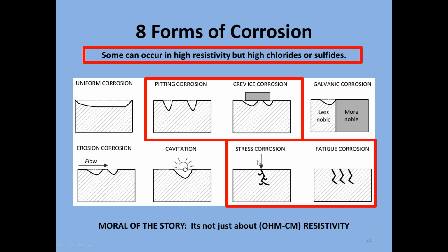so corrosion, you have to think of it in a way that there's general corrosion that occurs over a large surface area, and then there's localized corrosion, that's pitting in small localized areas. So when it comes to resistivity, it gives you a lot of information about the probability of general corrosion. But the salts, the high chlorides, high sulfates, sulfides, nitrates, those can tell you the probability for pitting and that type of localized corrosion. So it's important to know both.